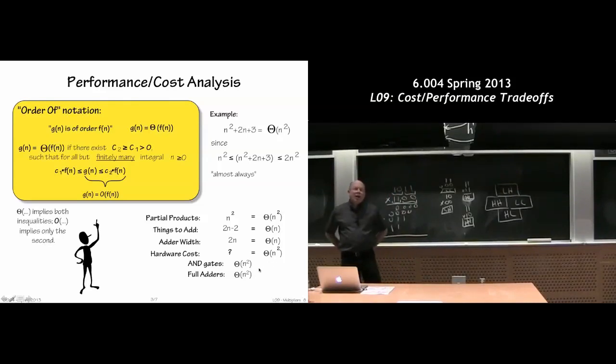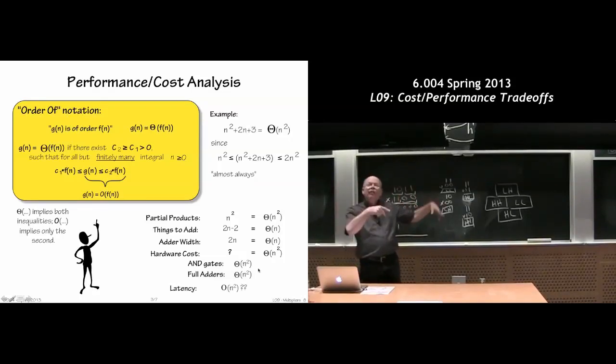So this is just a quick overview of how many pieces of hardware we need to build a multiplier. You might say, well, the AND gates are forming the partial products 1 bit at a time, and I have n squared of those, and then I have all these full adders. I need a lot of each individual building block for adding together bits in a column. I'll ultimately need about n squared of those adders.